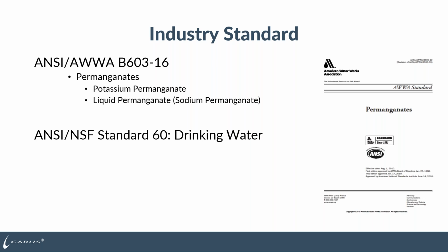If you're using potassium permanganate, it talks about particle size, which would be, is it dusty? It shouldn't really be very dusty depending on the grade of product you're buying, and then also what the concentration, the assay of those products are. You can get that standard directly from American Water Works Association.